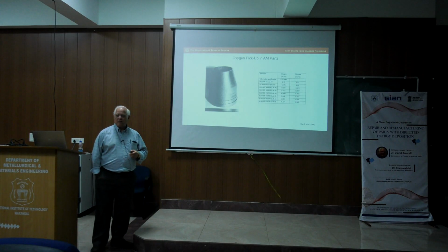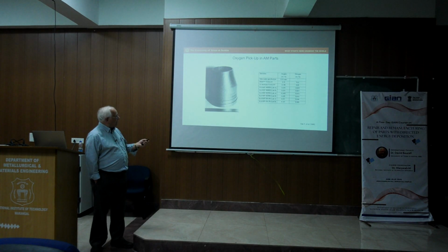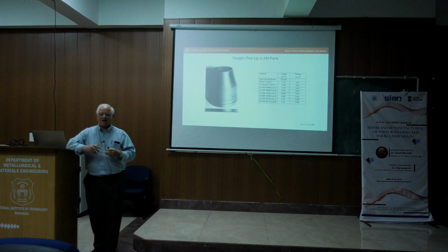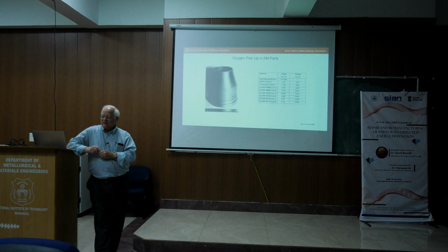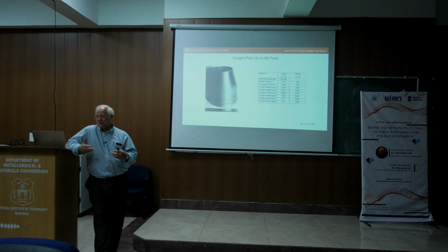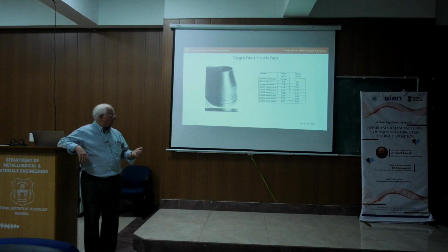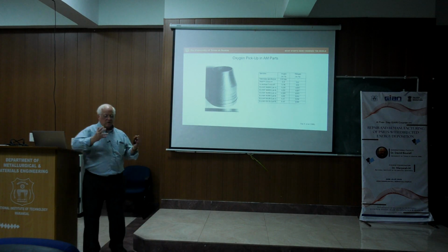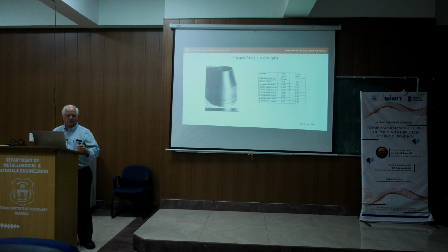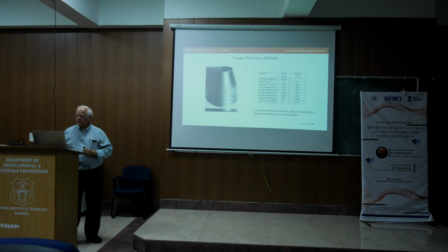So the solution that we did use was to substitute for this PREP powder an actual form of titanium 6-4. It's called ELI material. It stands for extra low interstitial, which means the interstitial here is the oxygen. So we got feedstock that had a lower oxygen content, and by running it, we were able to avoid this issue with the oxygen limitation.